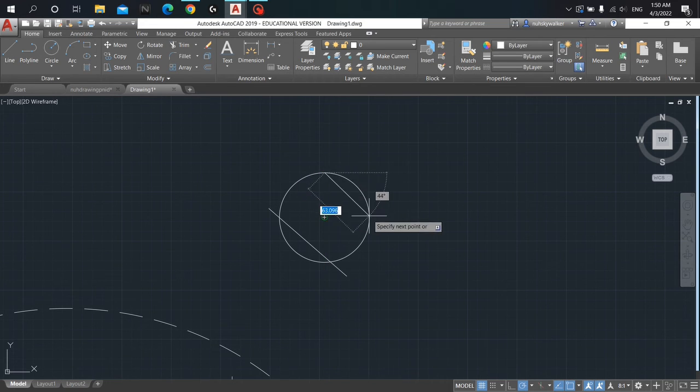Let's say if I want to go from here to here, see, it will automatically go to the centers, which is the reason why I advise you to start from the outer surface, from the outside of the circle, and pierce through the circle, just like that. So that we'll be able to trim this particular region later on by selecting all of the components involved, and then pressing enter. Trim all the unnecessary parts that we don't want.